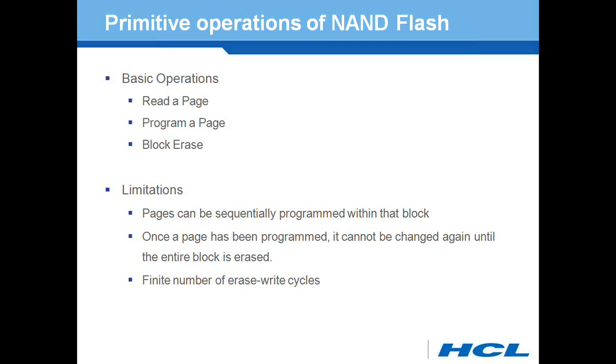Whereas when we do programming, again it's programmed on a page basis. Initially, the page at which the data has to be programmed needs to be transferred to the flash. The programming starts with loading of the address followed by the data. Initially all this information is loaded to the data register.